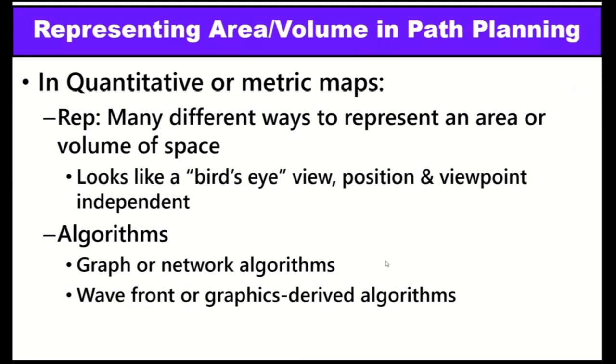Now, how to represent this path planning? There are many methods, or many times we have to develop our own algorithms depending on the task, the layout, and the area, and the designer has to select either topological or metric maps. Many of you may wonder: if a metric map is available, then why go to topological path planning? Or if metric maps are ideal and give correct positions, why do we need topological path planning?